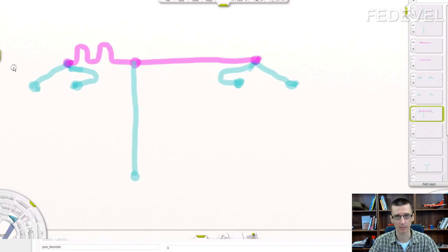Everything what we need to do is we need to adjust the length the way that all the signals in the address command control group have exactly same length from the processor to the memory chip. So everything what we need to do in the third step is to draw enough waves here to length match all the signals within group. Let's have a look how it is done in a real PCB.